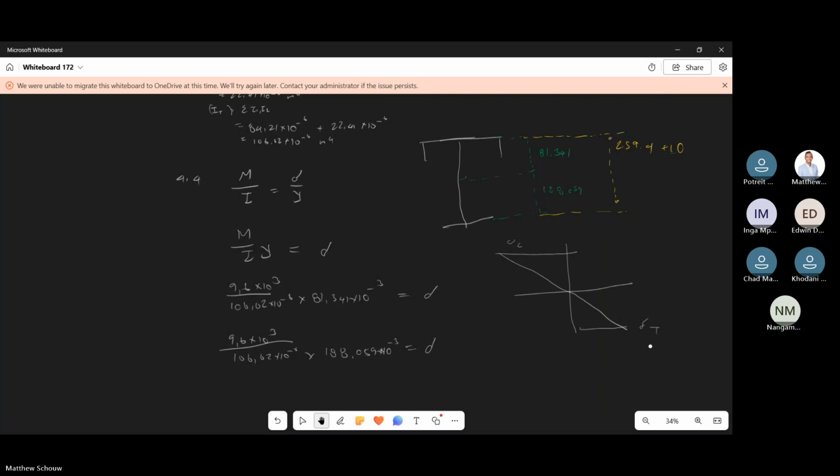Yes, sir. Yeah, but the difference now is that because the object is not symmetrical, the shape won't be evenly distributed. So you're going to find more stress where, I'm not going to tell you exactly where, either the top or the bottom. And that'll obviously influence our design. You're going to find out that the bottom side will have more stress than the top, basically.